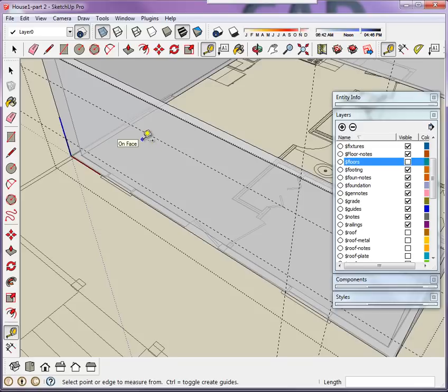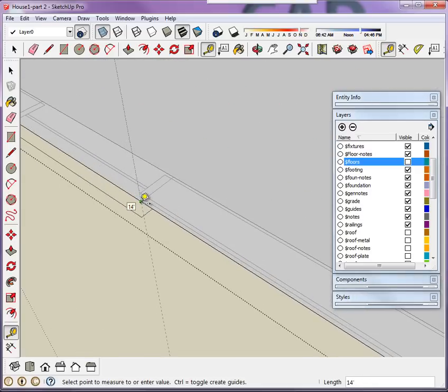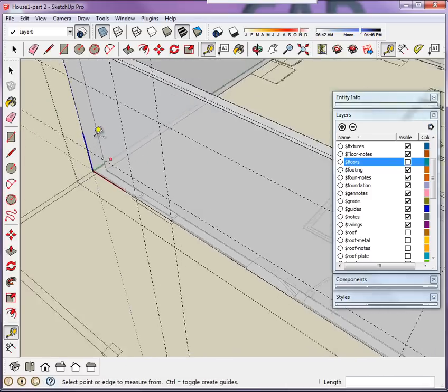So in order to be able to position it correctly on this side of the wall, all we'll need is just one more. Or we could do both guides. So snap to this guide again, drag along the face, shift, get in close, make sure you're on the outside face. Once again, using that previous guide, shift and snap.